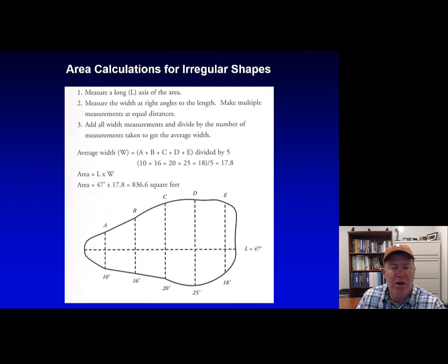It's just like with this area right here. We can figure out our square feet here, and if we were going to mulch this area at 4 inches depth or 3 inches of depth, we multiply by the 0.33 for 4 inches, which gives us our cubic feet. Divide by 27, we get our cubic yards, and we'll know how much mulch to get for this project.